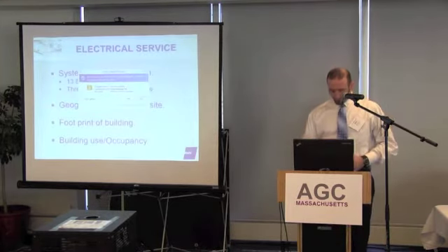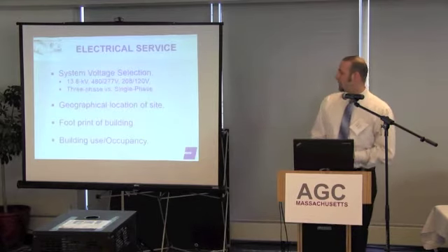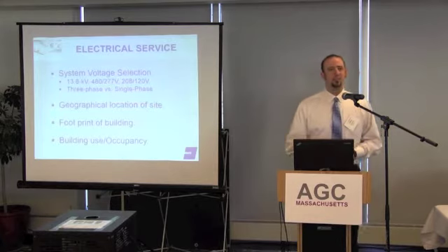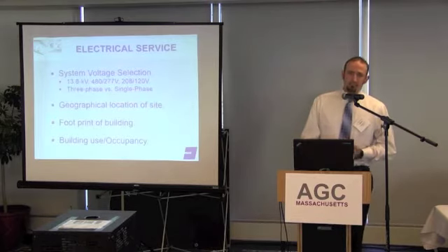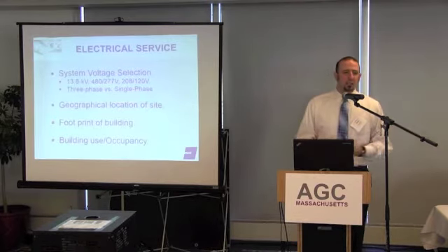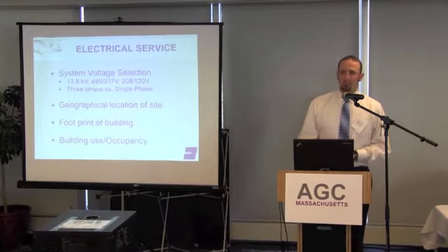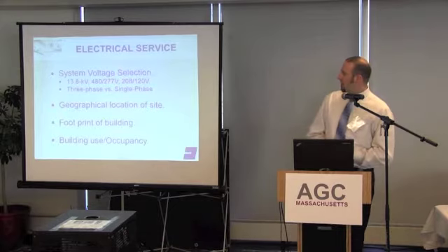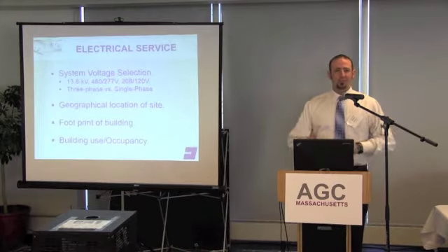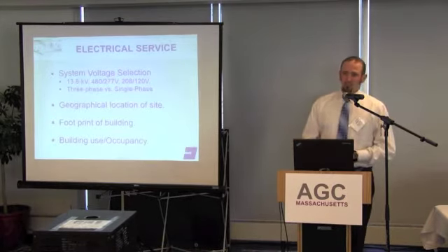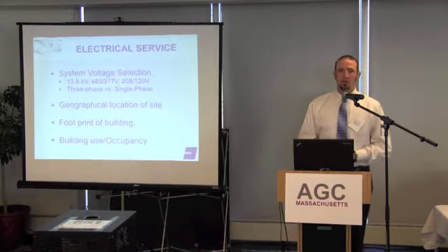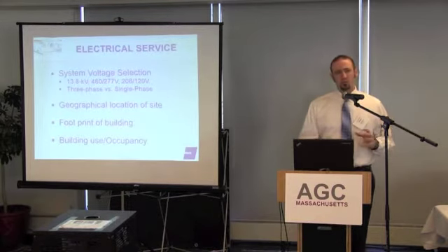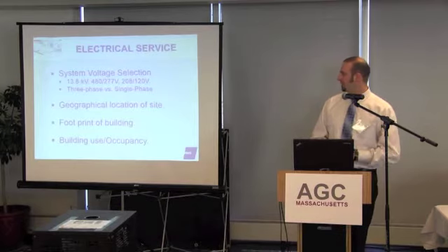And the 208/120s are used in residential buildings, residential mid-rises, and small to mid-sized office buildings. The 208s are not very commonly used when you're using chillers, large pumping systems, large horsepowers. Those are more used towards the 480 volt side.